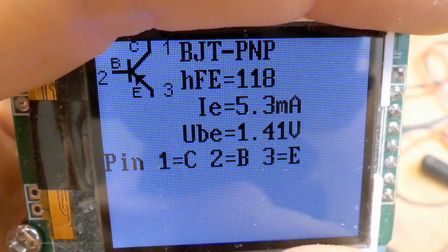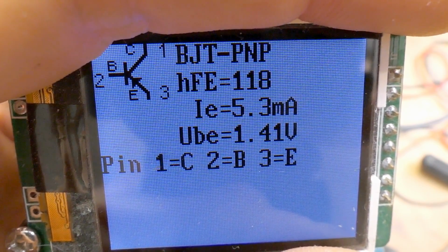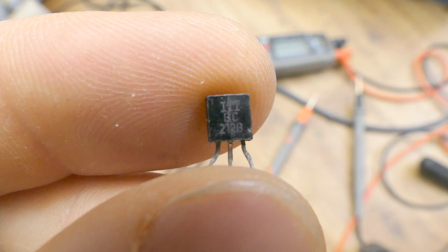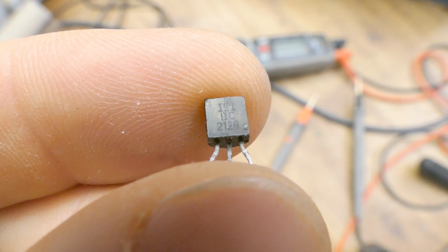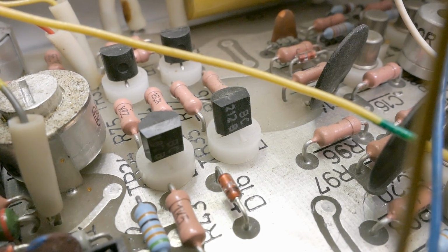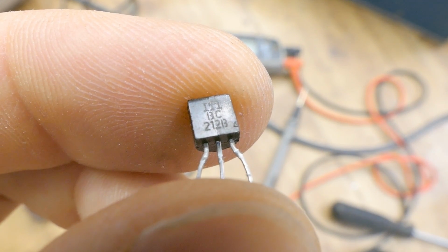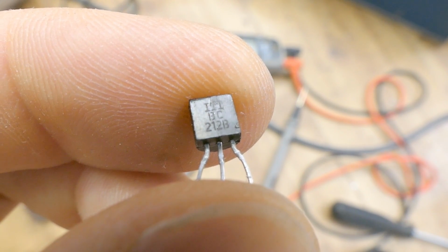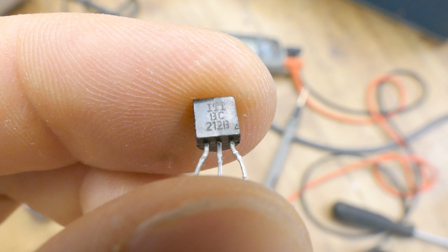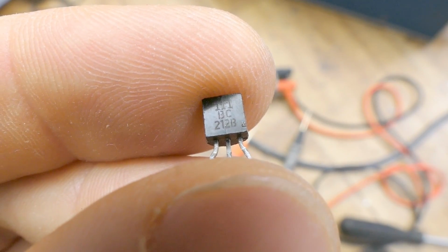There is just something sinister about this transistor, and the marking of it looks completely different than the other transistors. All the other transistors seem to have paint marking, which is vertically on them, and this suspicious transistor seems to have a laser marking which is horizontally on it. Was this transistor already changed?